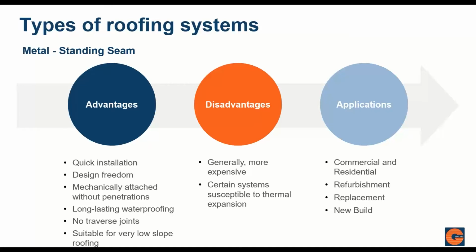And finally, for the metal systems, we're going to cover standing seam. Also very quick installation, and this offers designers huge design freedom, as we're not limited in terms of design, and we're not limited in terms of site access. If we are constrained on site access, this gives the designer complete open freedom in terms of the roll profile and the length. We can also taper or chamfer the edge of these panels without too much hassle. But the big advantage you get with this is there are no mechanical fixings in this system. It simply clamps together and you're not reliant on mechanical fixings.